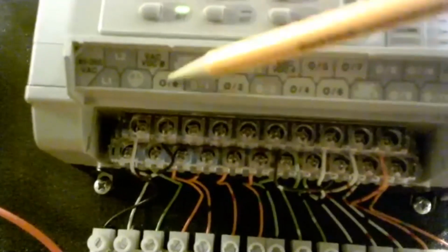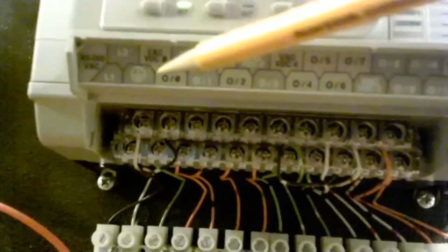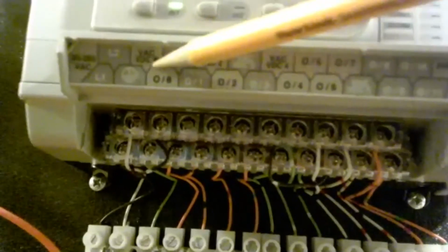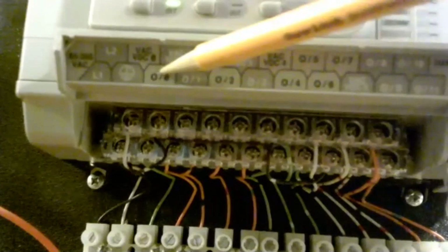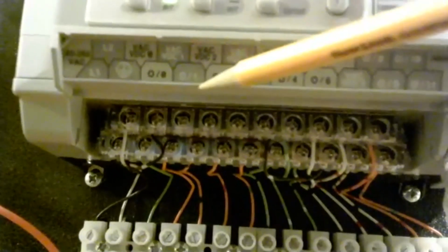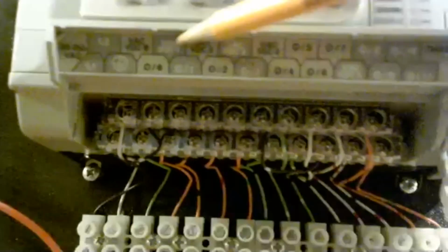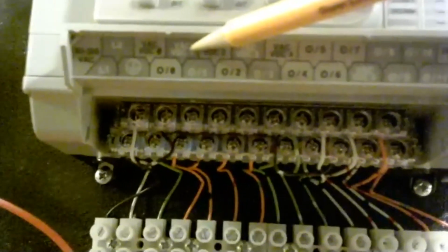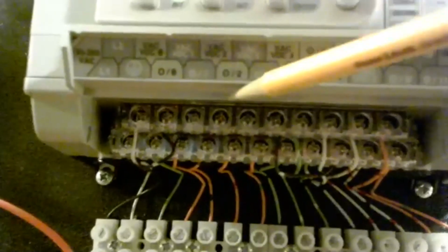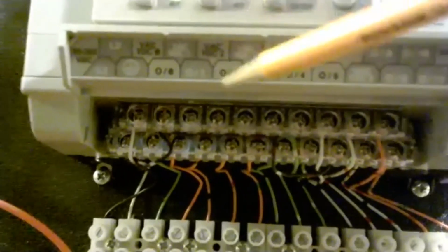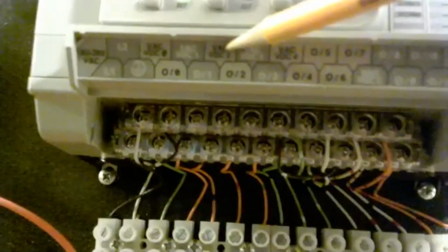This is a relay output. So you put 120 volt on that terminal, and then when the output comes on, it gets power from that terminal and connects it to here. This output 1 gets power from VAC1 or VDC1. You can put AC or DC on that terminal, and whatever's here appears right there whenever the output gets energized by the processor. And this output here, it gets power from that leg.